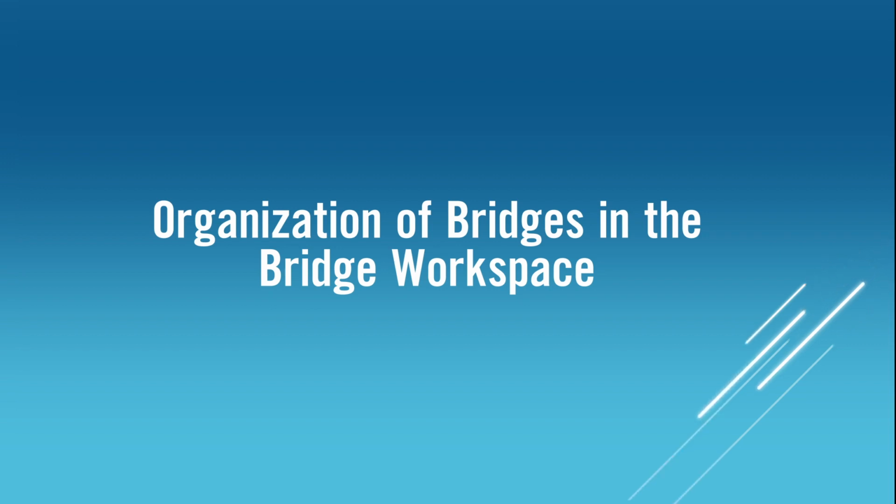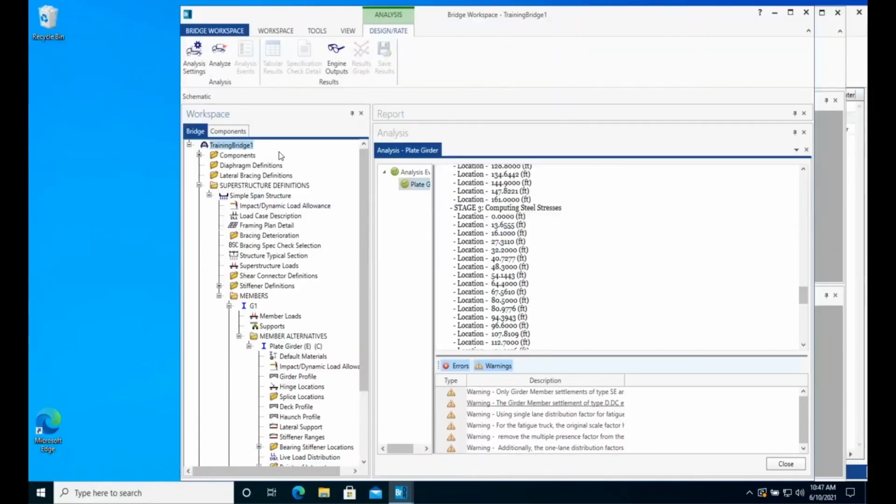We'll now review how bridges are organized and input within the Bridge Workspace. A bridge is a structure or group of structures providing continuity of a highway across an entire crossing. A superstructure is one or more spans that have the same structural type, such as a girder, truss, or frame, and for which a load acting anywhere within the structure affects all spans within that superstructure.